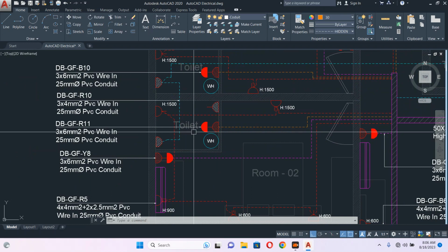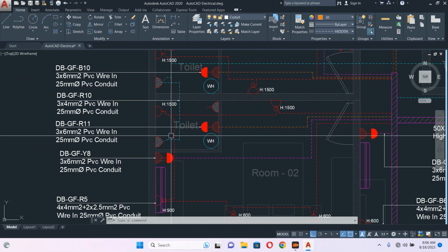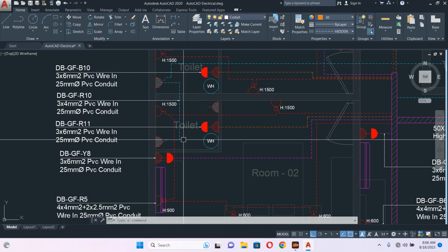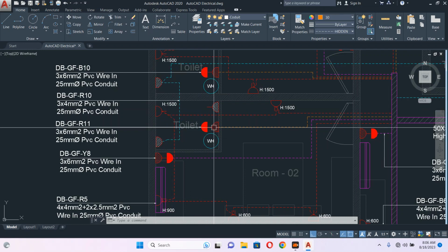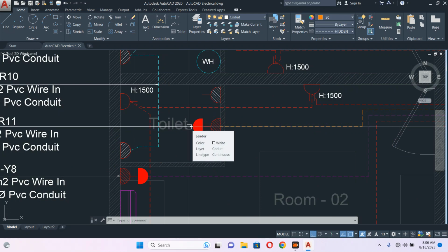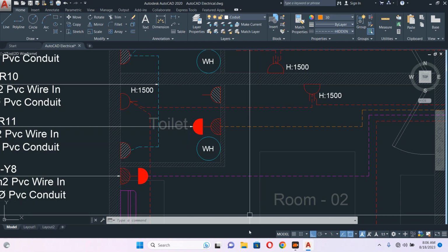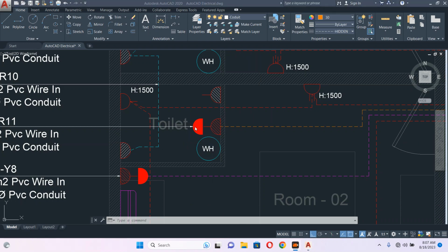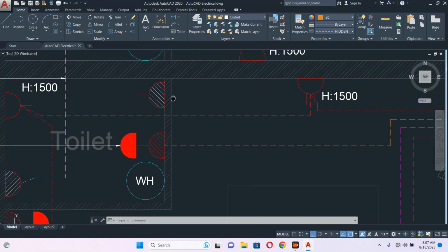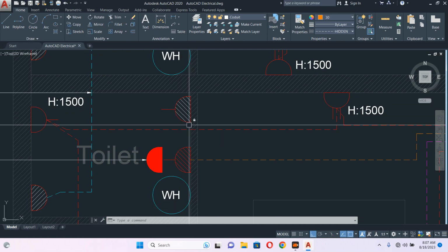These outlets will come in the toilet, washroom or bathroom, but you should arrange the outlet as per the arrangement of the sanitary ware. So I put one switched spare outlet for the hand dryer.